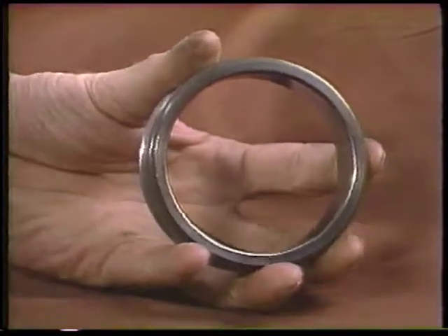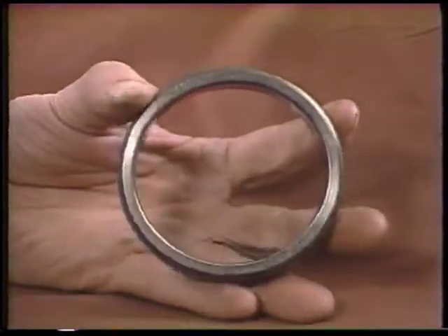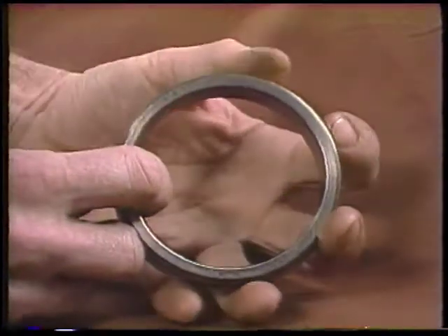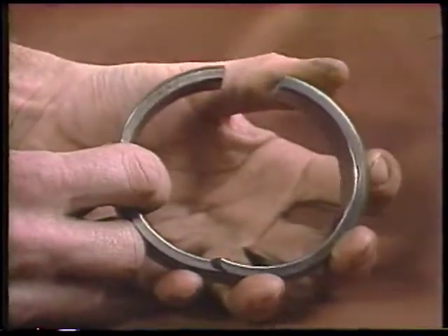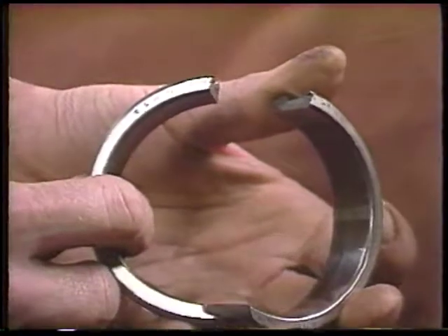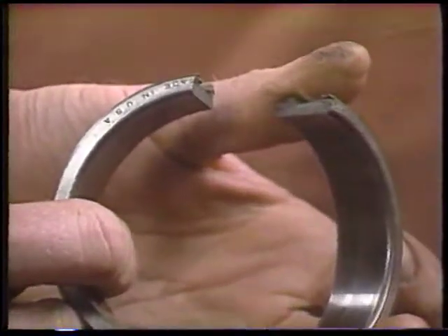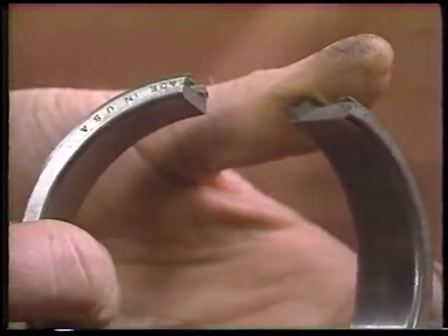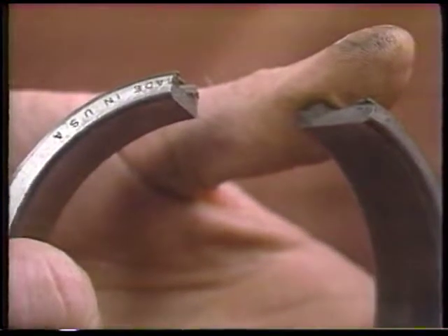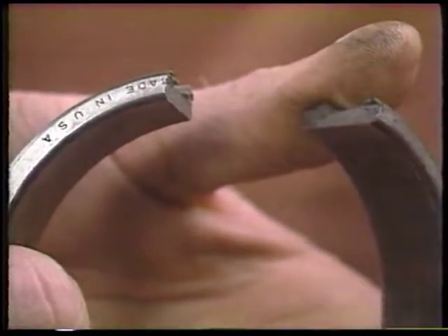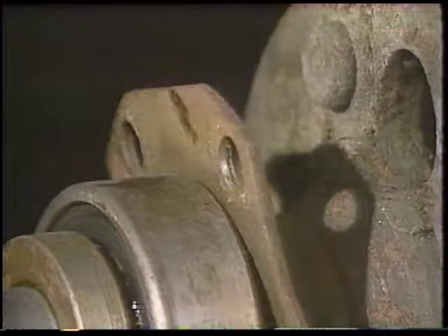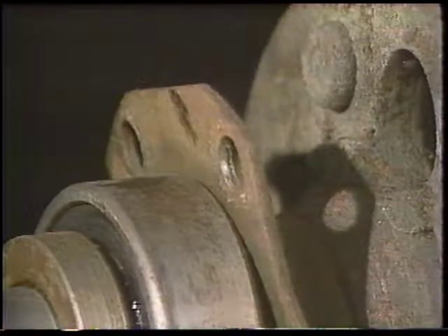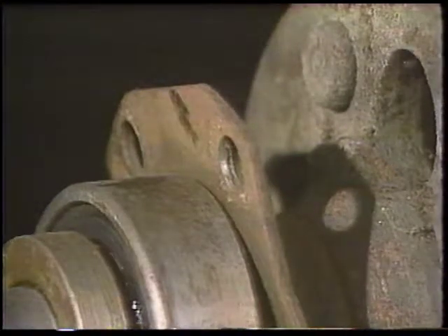If a bearing is pressed on incorrectly, it will be difficult to take it back off without destroying it. Or if pressed on incorrectly, a bearing may be only slightly damaged, so slight that the damage goes unnoticed, but the bearing still fails prematurely. In some cases, of course, improper press fitting can actually break a bearing. Keep in mind that some bearings, once installed, cannot be removed without destroying them.